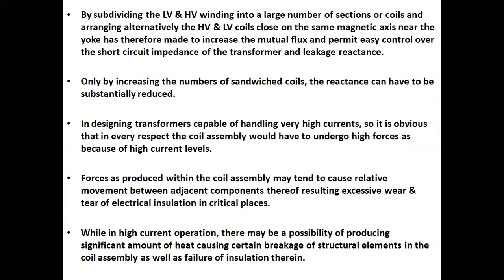In designing transformers capable of handling very high currents, it is obvious that in every respect the coil assembly would have to undergo high forces because of high current levels. Forces produced within the coil assembly may tend to cause relative movement between adjacent components, resulting in excessive wear and tear of electrical insulation in critical places.